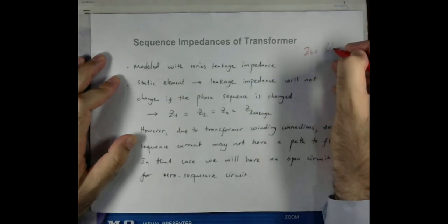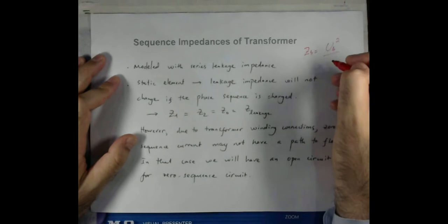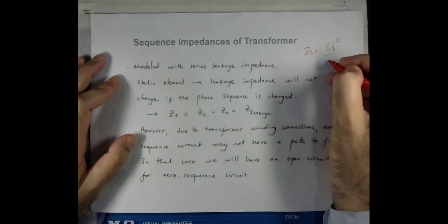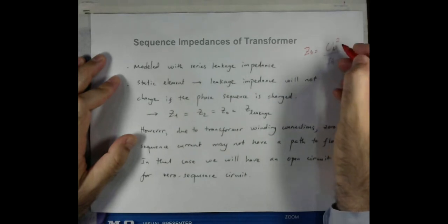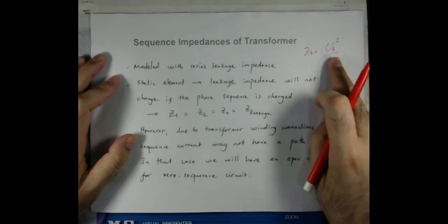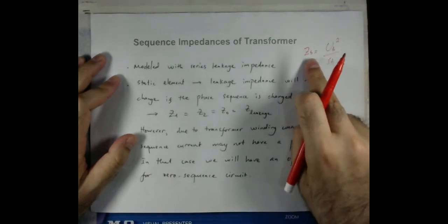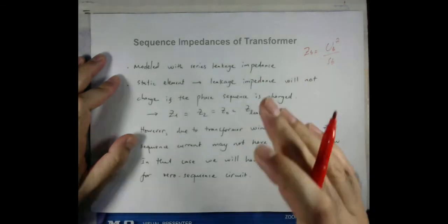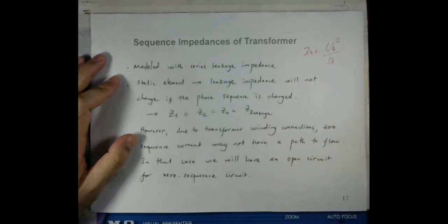related with the square of the nominal voltage divided by SB, and since transformers have at least two voltage levels, primary and secondary side voltage levels, for the same power rating the base impedance could be different, and correspondingly the actual impedance on both sides could be different. But once we have a per unit circuit, then if you remember, we discussed that the per unit impedance on both sides is the same.